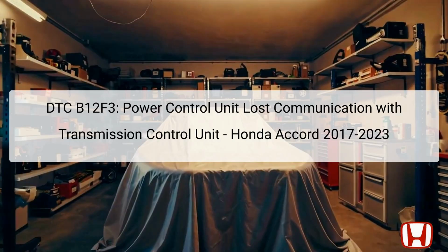The diagnostic trouble code DTC B12F3 indicates that there is a communication issue between the power control unit, PCU, often identified as the body control module, BCM, and the transmission control unit, TCU. The PCU plays a critical role in managing various electrical functions in the vehicle, whereas the TCU is responsible for controlling the transmission's operation. When this code appears, it suggests that the PCU cannot establish or maintain communication with the TCU. This could lead to issues in transmission operation and overall vehicle performance.